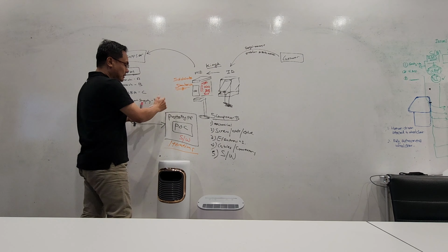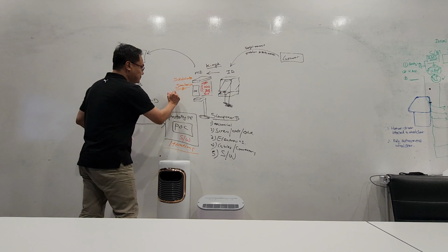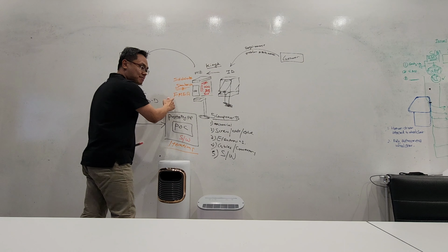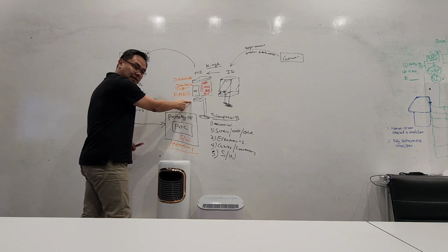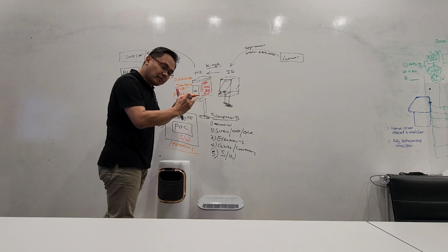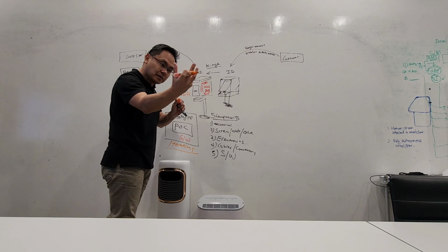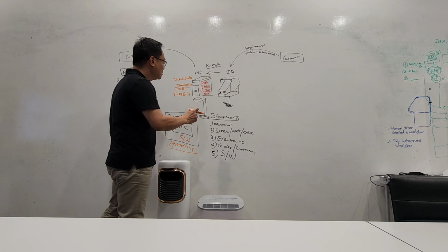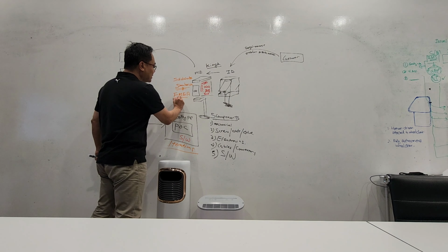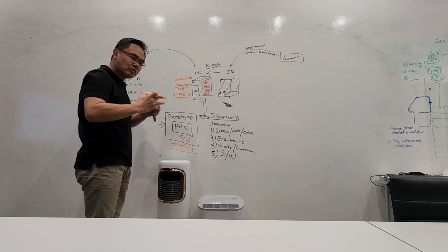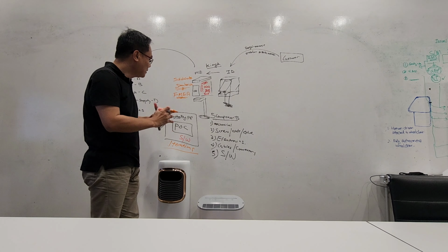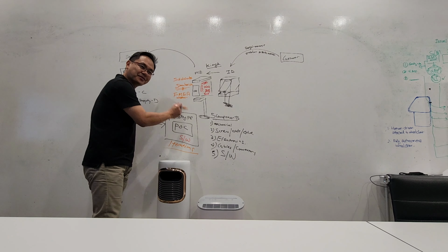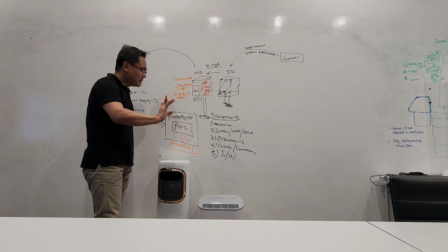Now, other than simulation, we also do FMEA, failure mode and effects analysis, to determine what kind of failure modes there are. If you do design A, what are the potential problems? If you do design B, what are the potential problems? So during the design stage, all these will be considered so that we filter out as many problems as possible to ensure a 99% prototype the first time. Of course, the 1% you cannot avoid.